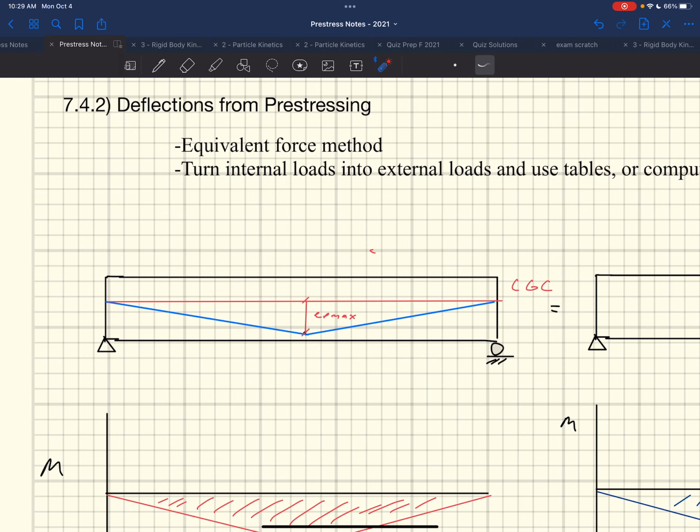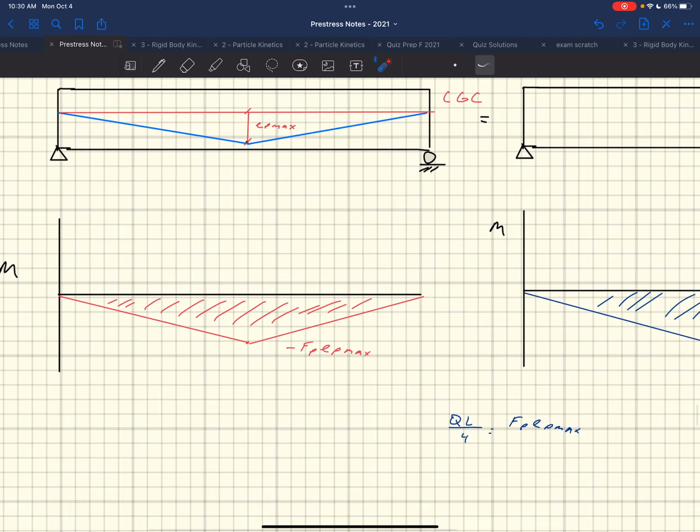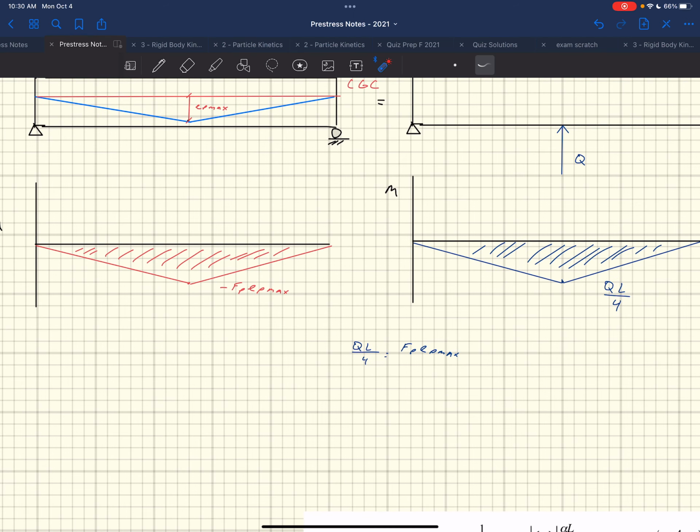The other thing to keep in mind, these are always very exaggerated. Usually it's like 10 inches of a drop over 60 feet of span or something. So is it okay to have this? Yes, because that vertical component is very small compared to how long the span is. And these are never drawn to scale. If we drew that to scale, it'd be way longer, and you'd barely even see the depression in it. Absolutely great question. At the end, we have one summary of things that we didn't account for that maybe weren't completely correct, and that's one of the things we bring up.